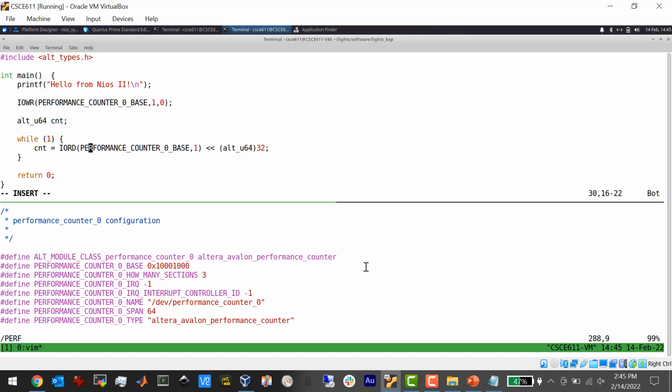It's kind of hacky, like the reading and writing action, when you read or write, it does two different things. It's not like you're writing a value and then you're reading that value back. That 0 that I just wrote to it is gone. It never actually got registered. It was just sent as a signal to start, right? It wasn't actually writing the value of 0, which is why now I'm doing an I/O read, which is the opposite of the I/O write to the same address, and yet I'm getting a different value.